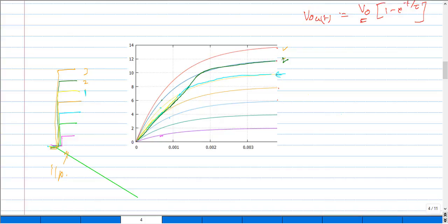So in each of the cases, the output never follows initially the exponential curve that we have drawn, okay? And later on, it settles down to the exponential response. So in 3 cases, so basically 1, 2, and 3, the op-amp basically suffers from slewing. Okay, it loses its linear property in these regions.